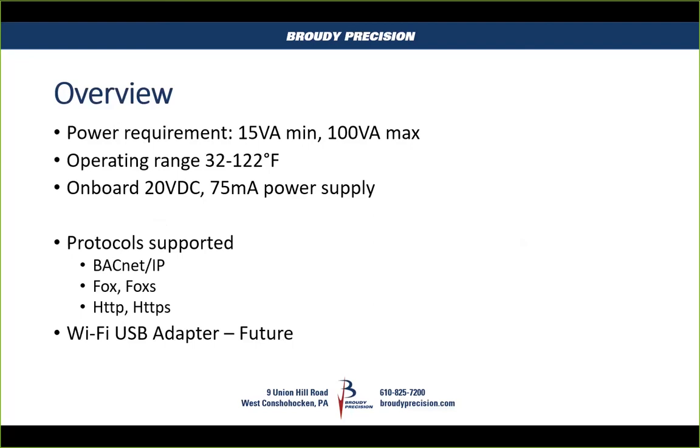And there's also a terminal pair marked not applicable, and that's actually an RS-485 port that's not used at this point, and I'm not sure if and when it's going to be used, whether it's going to bring in a couple BACnet MSTP devices, or if it's just not going to get used at all. There hasn't been any talk, and they just kind of stay away from it. It's just there, but does nothing.